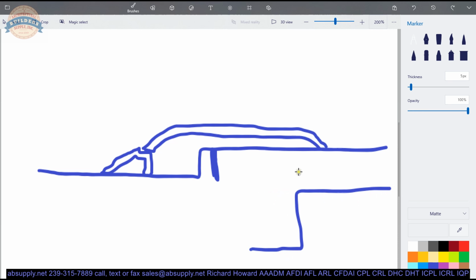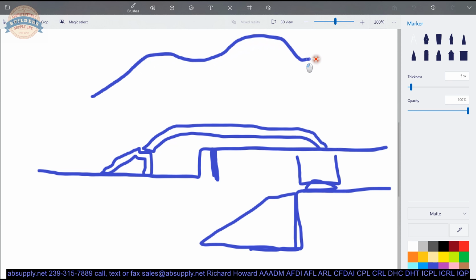And my recommendation is that we bring the doors here, put in a 1/2-inch threshold here, and then literally get large pieces of 8-quarter lumber and cut them to give yourself a transition like this. The issue is that these openings are fire rated, and there is a large offset threshold that has a vinyl insert in it.